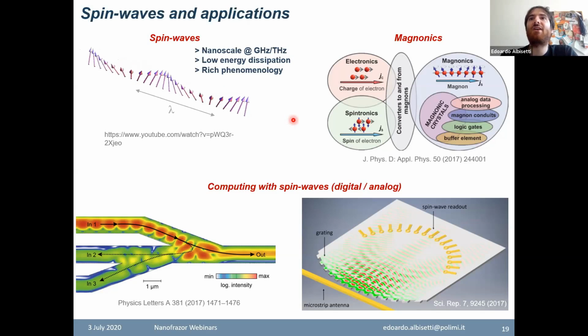Spin waves are naturally nonlinear, and so for reasonably high intensities you can have a lot of nonlinear effects that in some cases you can use for building non-conventional computing platforms, but in other cases are detrimental, for example, to your linear interference pattern. So you have to really control very well the systems where the spin waves are propagating to be able to use spin waves for computation.